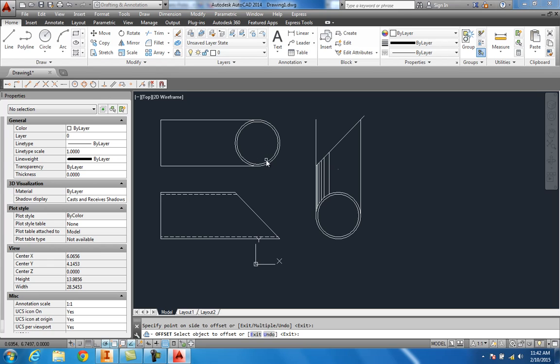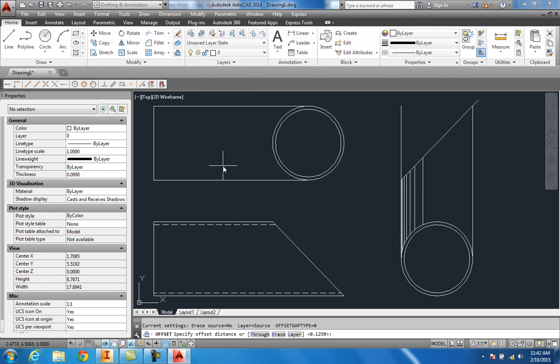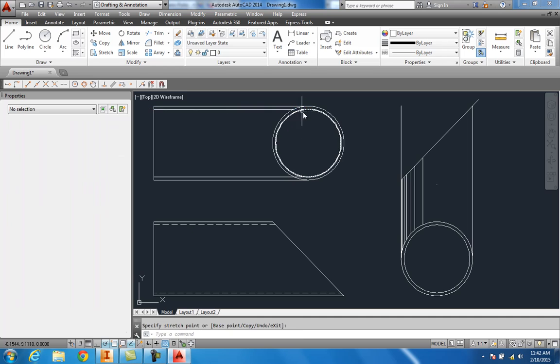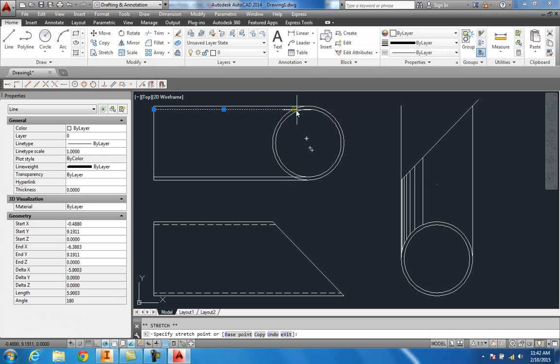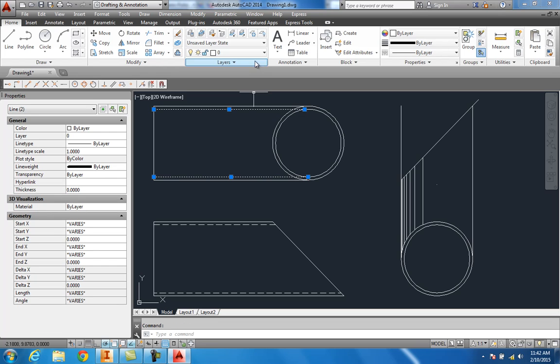So that right there would be actually what this thing would look like on the top view, the front view, and the right side view. And also on this one too, on the top, I'm forgetting one thing, is we've got to put in our offset to show our material on the inside. So again, get that done, grab that and pull that line back to there. It'd actually be all the way up there to that edge, just like it is. That looks great. Grab that and then change it into your hidden line.